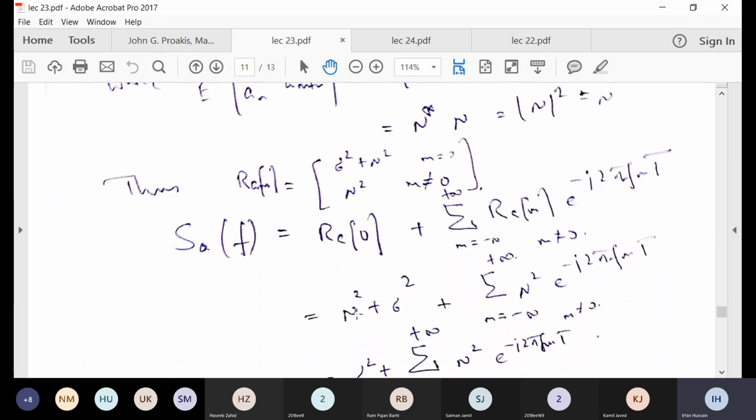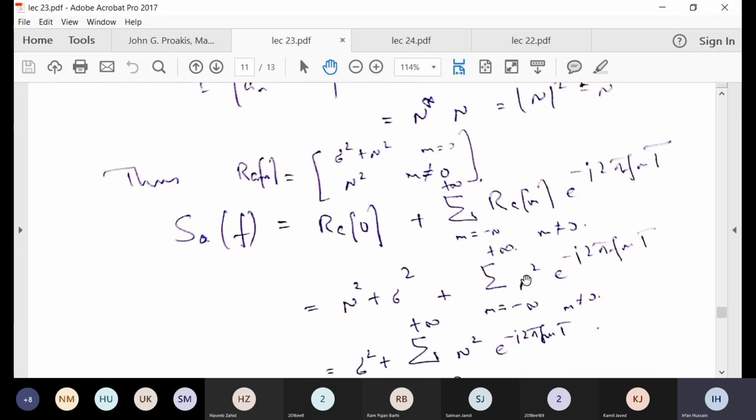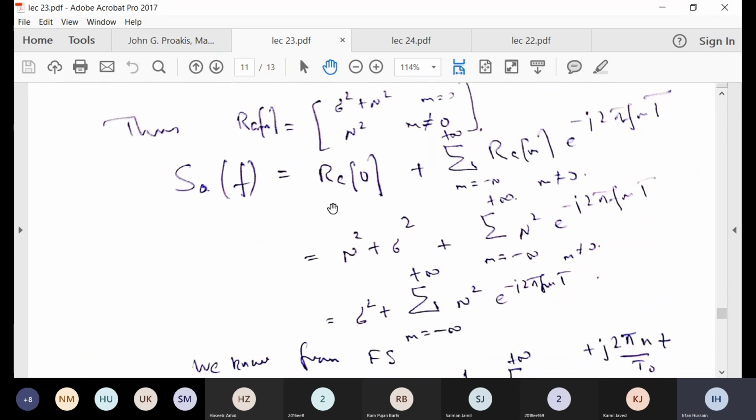So your SAF, which we have derived, is the Fourier transform of these coefficients. So I put the coefficients: for 0, I put this value, and when m is not 0, this value is mu squared. This comes out to be like this. So I can take sigma squared, and put mu squared also here, because this was for m not equal to 0. But now if I put mu squared here, and you have m equal to 0, you can very well see that this will be simply 1.